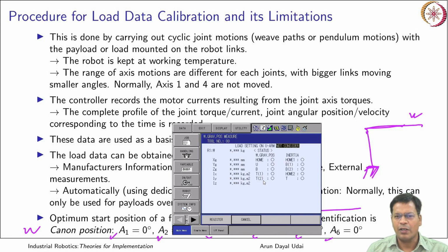Okay, you see this is all star, star, star. Now it is asking me to consider the added mass if it is there in this, because now I am going to perform tool calibration, tool load calibration. Okay, so it is also asking whether to consider any additional load if it is there on the U arm. So it may be considered or it may not be considered. Okay, so if I select consider, it does some sort of motion for the home position.